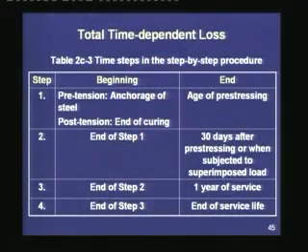The third time step starts from the end of the first month and ends at the first year of the service life. Here also what we observe is that in the first year of service life the losses can be substantial, and hence we need to recompute the pre-stressing force after the first year of the service life.